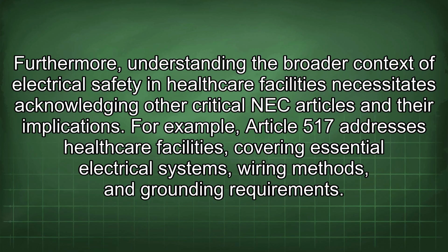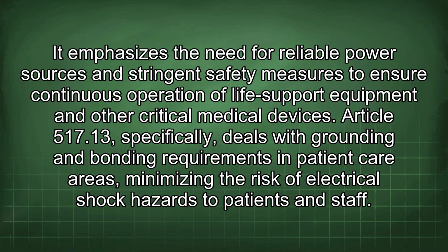For example, Article 517 addresses healthcare facilities, covering essential electrical systems, wiring methods, and grounding requirements. It emphasizes the need for reliable power sources and stringent safety measures to ensure continuous operation of life support equipment and other critical medical devices.